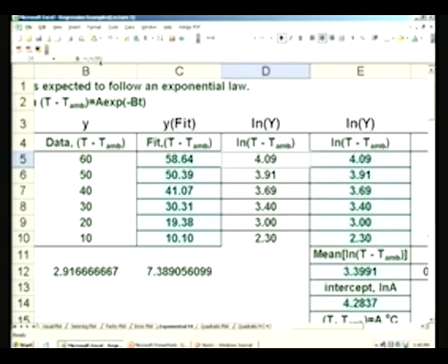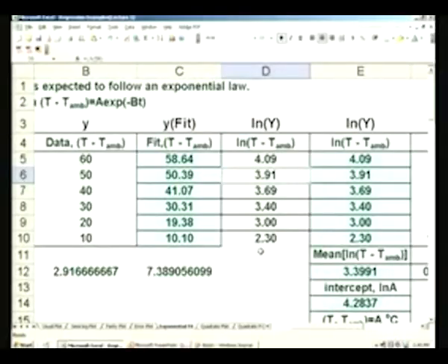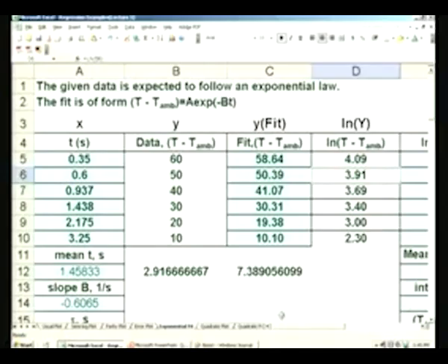This will be the logarithm of b5, the next cell is the logarithm of b6, so it has gone to the next cell. Copying the formula also changes the reference to the appropriate cell. In the previous case it was b5, it became b6 and so on. So it will automatically run down, calculating as we go by taking the suitable reference to the suitable cell.